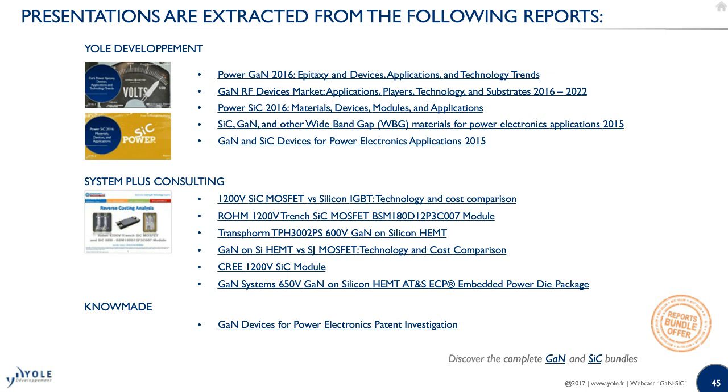Okay, and the same question for gallium nitride. What is the driving market for this material? So far, the market is very small, and there are a bunch of applications. In the future, we think that the primary application will be power supplies and adapters in the consumer and telecom regions. There will also be applications for wireless power, envelope tracking, and the low voltage range.